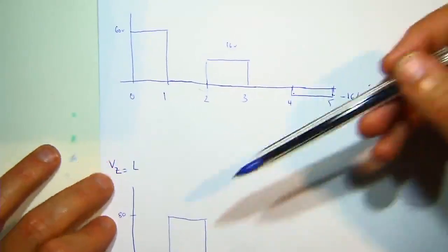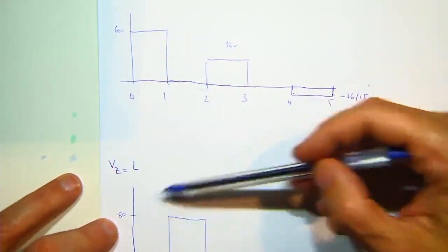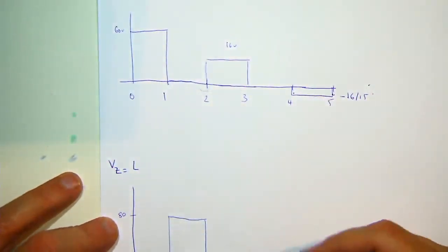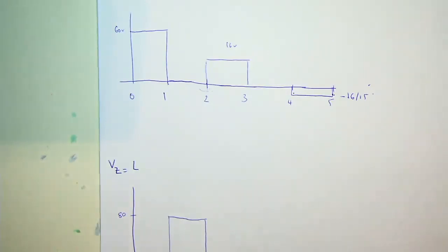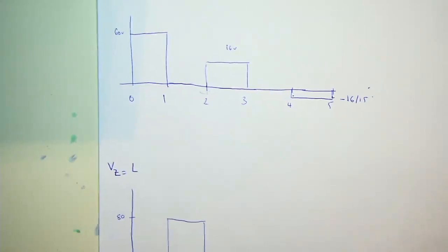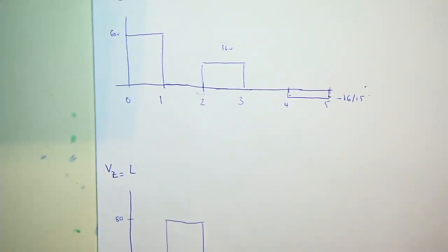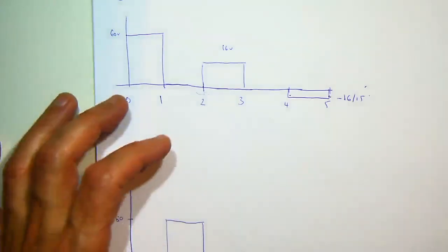At the load, if you go through the calculations, you've got an initial 80 volt positive going pulse. You now have a pulse which is minus 16 on 3, between 3 to 4 microseconds, and between 5 to 6 microseconds, you've got a pulse of magnitude 16 on 45.